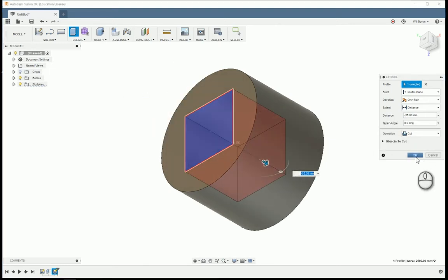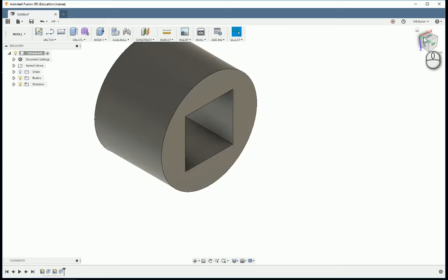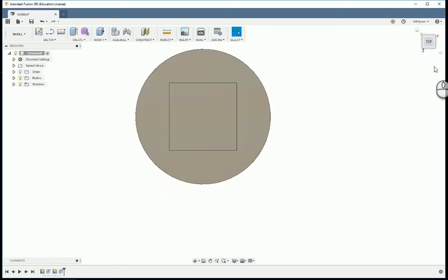So if I were to cut, I'll leave it. Now you can see, looking from the top down, really the side down, I've now physically removed part of the object. And that's what I'm talking about with either building up and subtracting away, or designing from the ground up what you really want. This is the way to make a through hole. This is the way to make, like if you've got to put a screw into an object, you would make a hole however deep you want it. And you can cut it away quickly and easily without using one of the other tool sets.